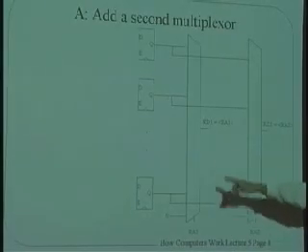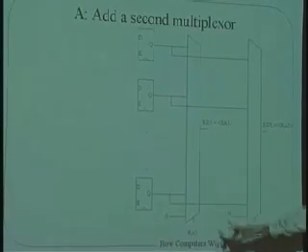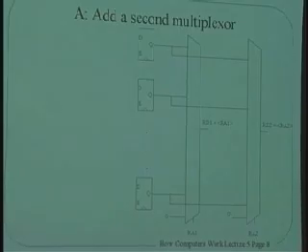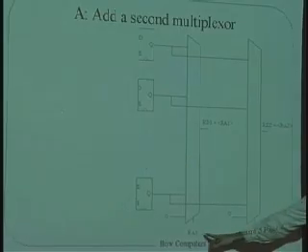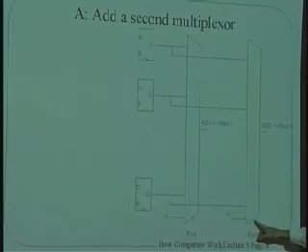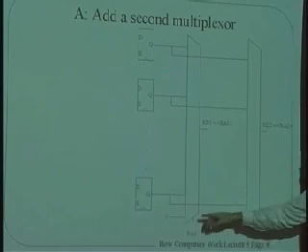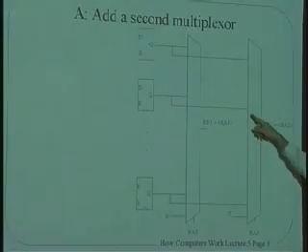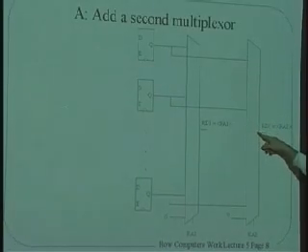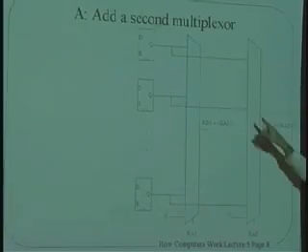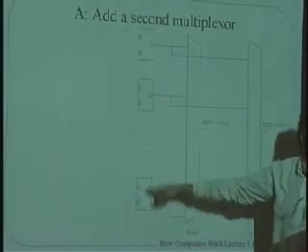Notice that there's only one set of registers, but there are 2 different ports for accessing them, 2 different views looking into the register file, and we get to examine 2 different registers simultaneously, one being chosen as RA1 over here on the left, and another one being chosen as RA2 over here. And for instance, this one could be choosing R0 to get steered to the output here, while this one over here chooses R1 to be steered to the output here, and each one would get a different piece of data from different registers that are over here on the left.